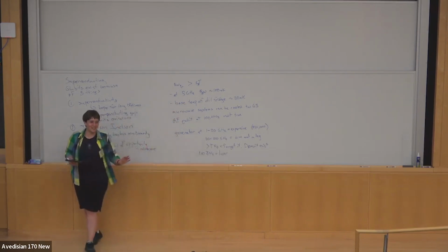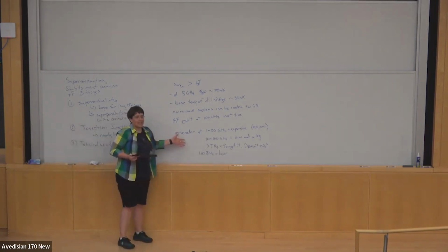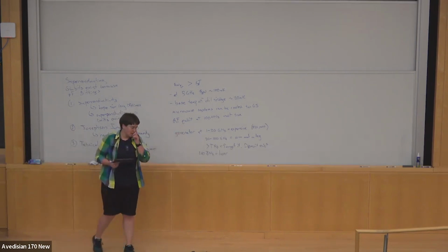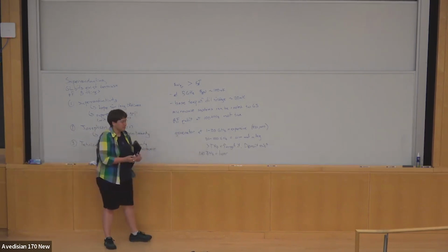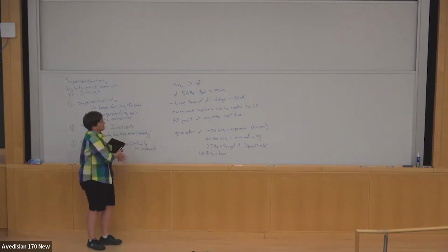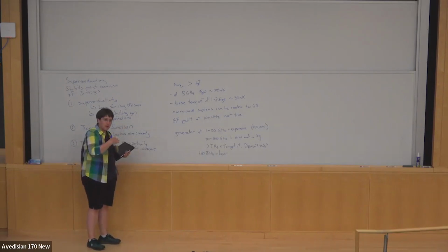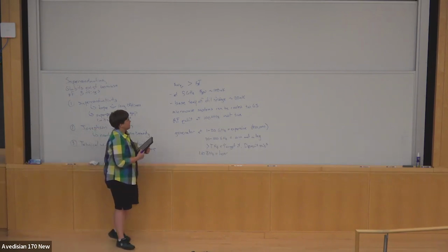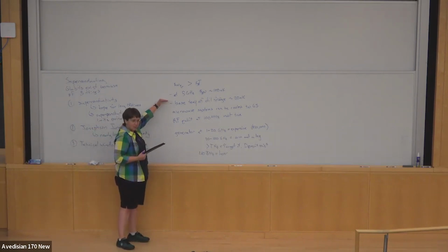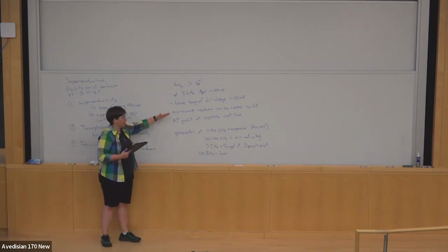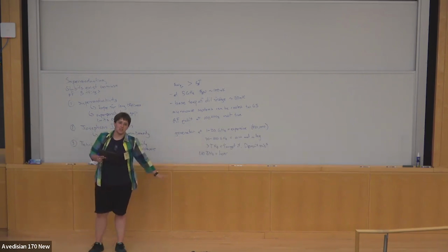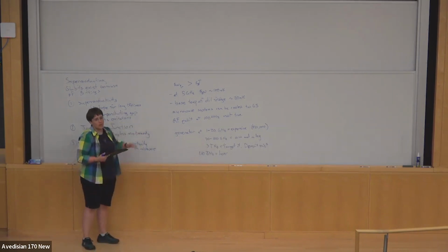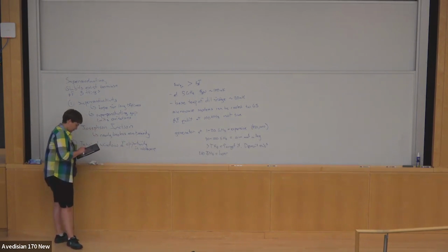There's a lot of reasons to want to go to higher frequency, but basically, I can't get the classical hardware that would be needed to run a qubit in that frequency range. People are working on this. People have pushed up into this kind of a range, but at least my feeling really is that the field of superconducting qubits lives in this 5 to 10 gigahertz frequency range, because it's trying to go in between this 20 millikelvin base temperature of the dilution refrigerator and this 20 gigahertz limit where SMA connectors and generators start crapping out. So there's this very narrow window of opportunity in the microwave regime.